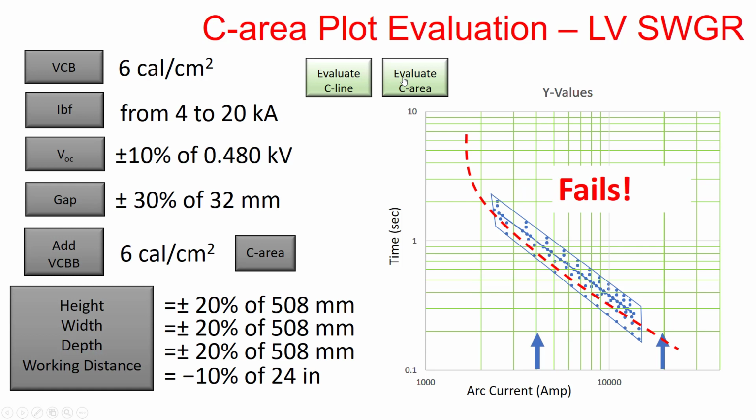which is the reason why a single line cannot be used to evaluate the energy response on a time current characteristic curve. This failure is caused by the fact that the arc can live in different forms with longer gaps and different electrode configurations. Therefore, an adjustment of the time dial settings for this relay will be necessary in order to accommodate these other potential forms of the arc.